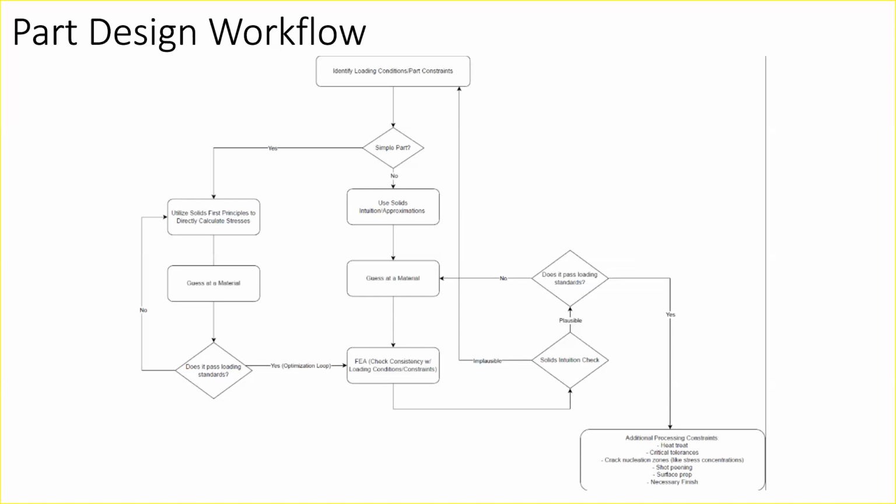As you go into materials like composites, it becomes a lot more complicated since you have two or more materials, a matrix and some kind of binding agent. For example, you might have carbon fibers and an epoxy in a standard layup. So it doesn't behave similarly in all directions. So one, it's super hard to characterize. And two, any layup that we do in-house is going to be a lot more inconsistent than a very precisely alloyed metal that we get out.